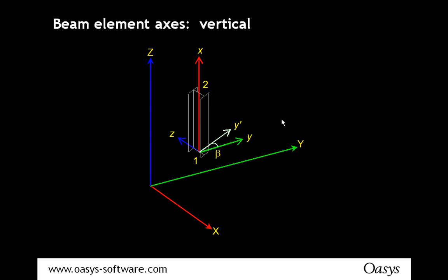there is no vertical perpendicular direction, and so you have to have a new rule which has the local Y parallel to the global Y. There is a straightness tolerance or verticality tolerance which is set in your preferences, so I think it's within a couple of degrees by default, and this rule then takes over.